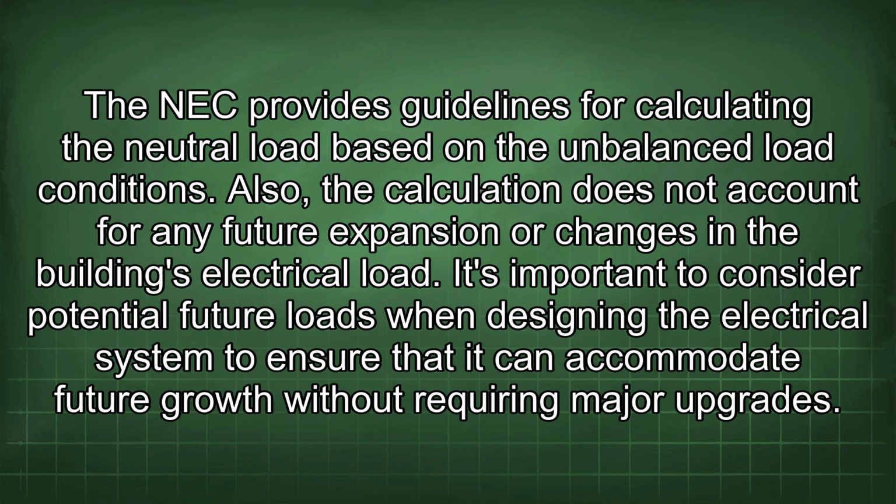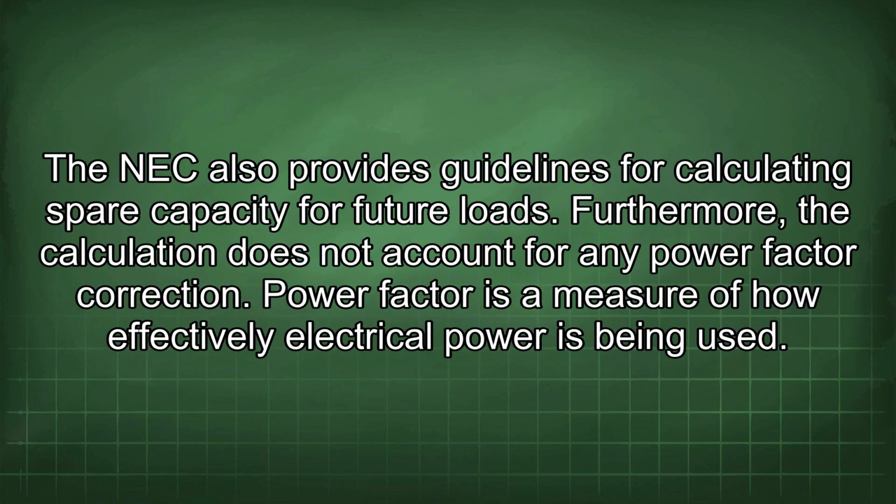Also, the calculation does not account for any future expansion or changes in a building's electrical load. It's important to consider potential future loads when designing the electrical system to ensure that it can accommodate future growth without requiring major upgrades. The NEC also provides guidelines for calculating spare capacity for future loads.